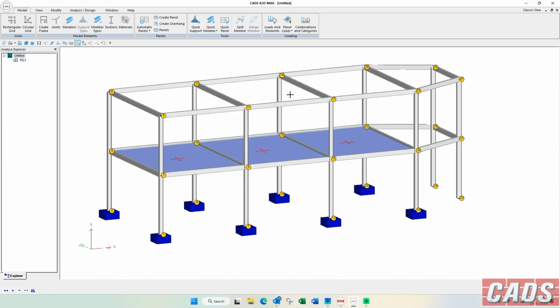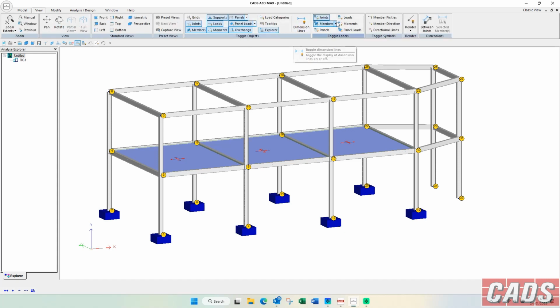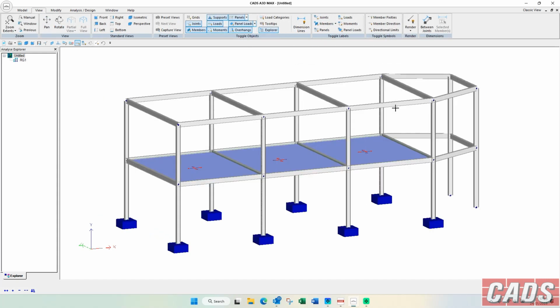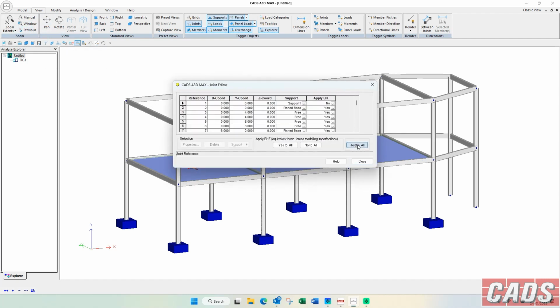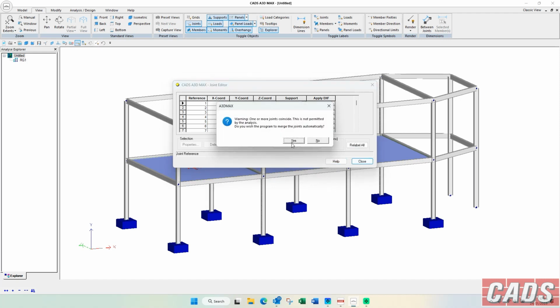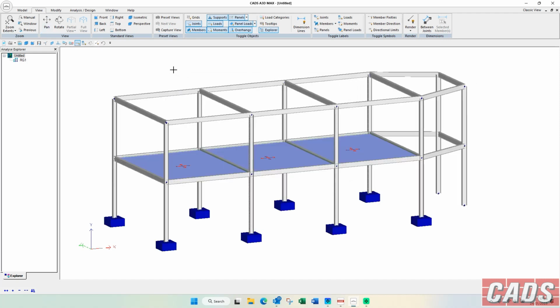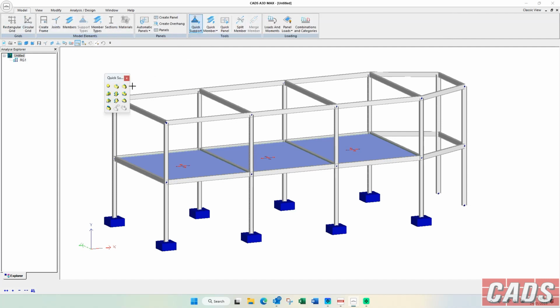So we've joined two frames together. One is done by the program, and then the horrible bit's been done with DXF. Just saves, again, a bit of time. We can turn off those joint labels. Now, one of the things I want to make sure of is there's no duplicate nodes. A clever trick here is to go into relabel, and the program actually gets rid of any duplicate nodes for you, so everything's clear. And then we just need to add in quick member here a couple more supports. And bottom, there we go.